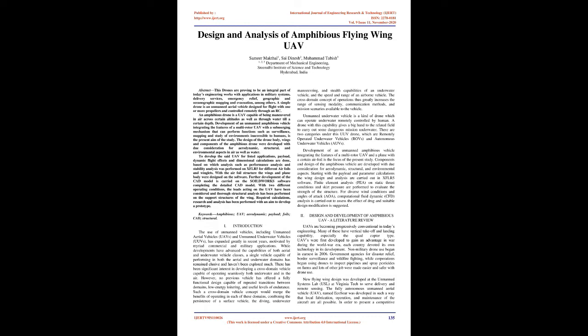To develop the said UAV for listed applications, payload, dynamic flight effects and dimensional calculations are done, based on which analysis such as performance analysis and stability analysis was performed on XFLR5 for different airfoils and winglets. With the airfoil structure, the wings and plane body were designed on the software. Further development of the CAD model is carried on the SolidWorks software, completing the detailed CAD model.